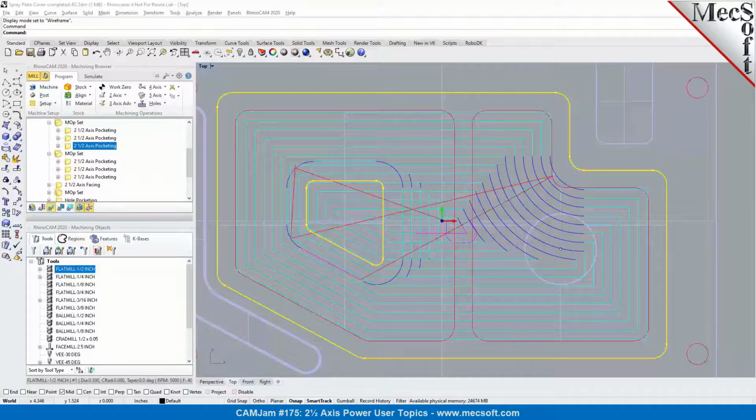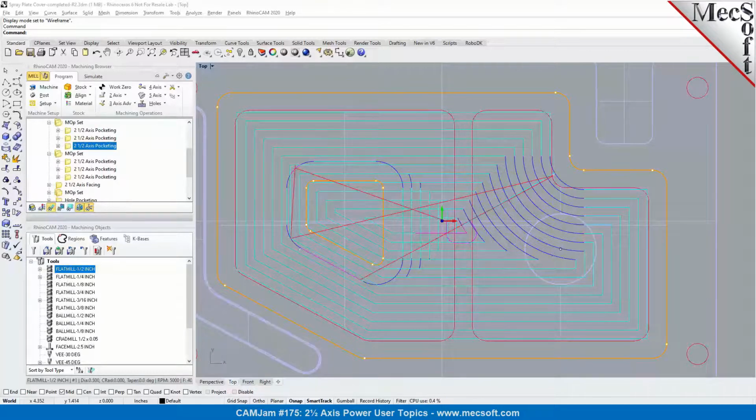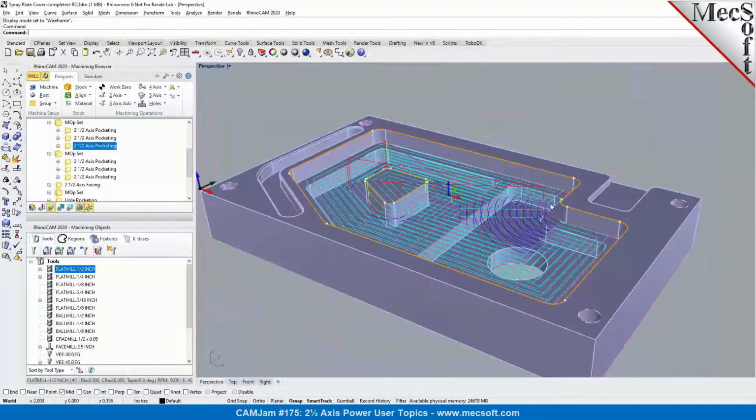Sure. If you're using a very tight tolerance, one of the things you'll notice is you'll have more go-to motions. If the toolpath is being output as linear motions, you'd end up with more points, more point-to-point moves. It's possible on some machines or controllers that the control may not have enough look ahead, and the machine could stutter or slow things down.